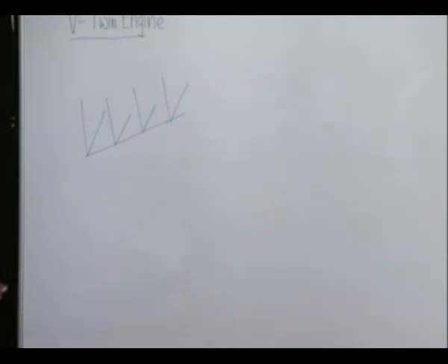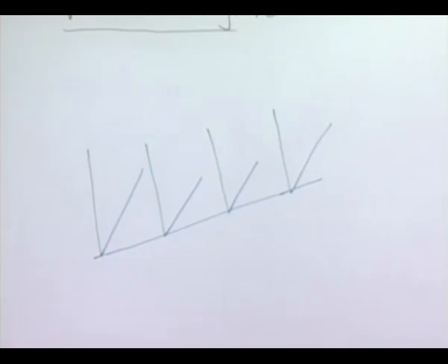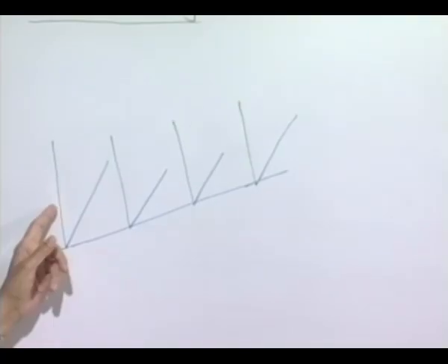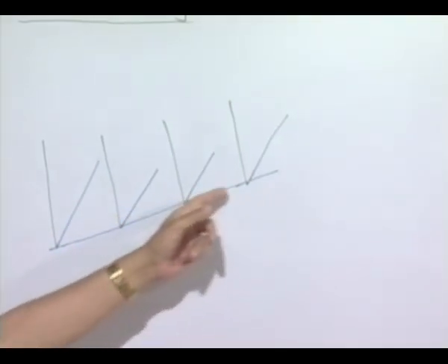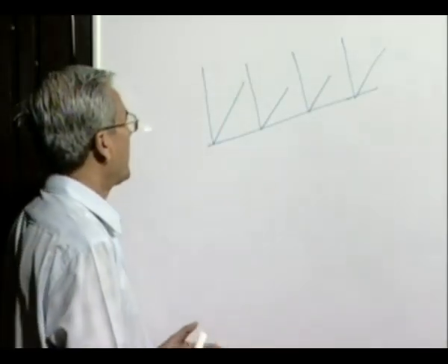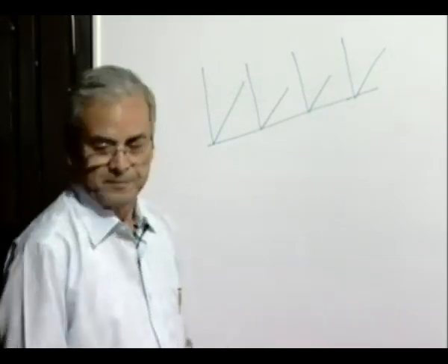As in the last session I showed that for a 6-cylinder 4-stroke cycle engine, it is possible to arrange the firing order in such a manner, that means the crankshaft will be of such shape that the primary and secondary both forces and moments are completely balanced among themselves. So, here also you will find by suitable arrangements such an engine, maybe it will be 8-cylinder engine, each V will have 2 and there are 4 V's. It will be possible to completely balance up to second order the unbalanced forces and moments.